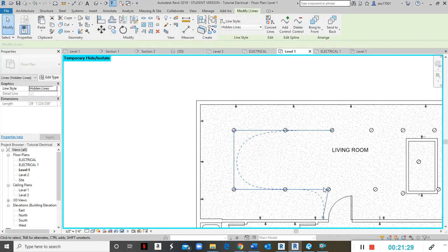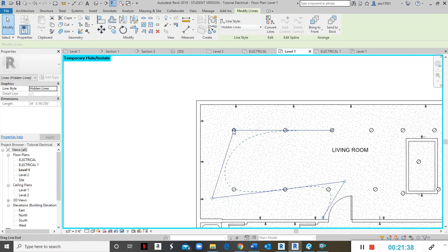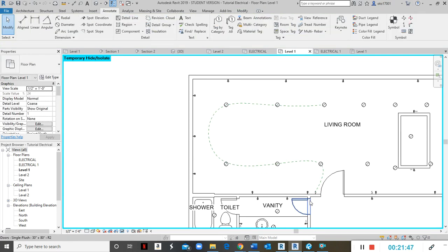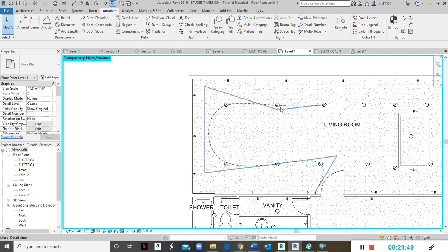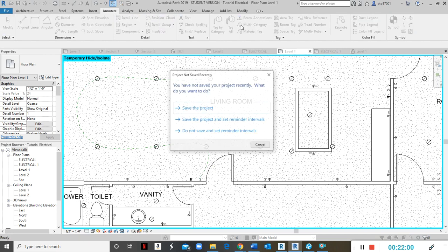It looks funky, but when you click on this, you can see it shows up, and you can move the nodes around. Okay, so it means that this light goes all the way. You do not bring the line back to the switch. No, you leave it on the last one, so that the power goes from here and then turns this on, turns on, and then turns it off. Yep. So detail line.